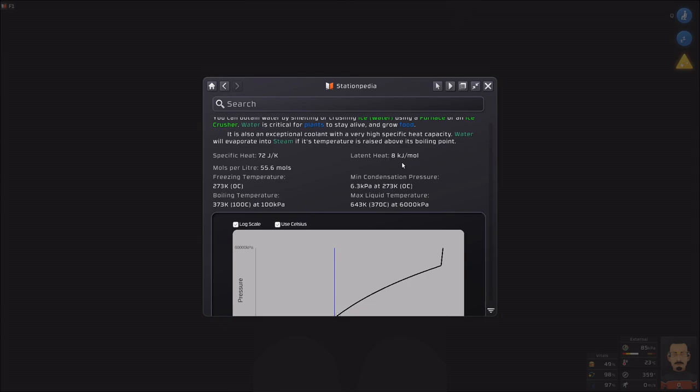That leaves, depending how much was in the evap chamber, say 1 mole of water evaporates. There's 10 moles in there. So that means, and it was at 25 Celsius. The whole thing was at 25 Celsius. So that would mean out of this 8,000, 720 of it was spent cooling the whole thing back down to 20. So that means I have 7,280 joules left to go.